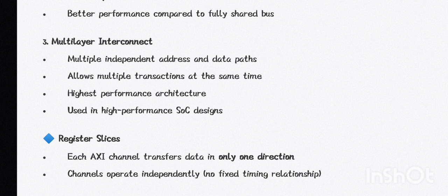Register slices. Each AXI channel transfers data in only one direction. Channels operate independently. What is a register slice? A register slice is a pipeline stage inserted in a channel. It helps to improve timing by breaking long paths.